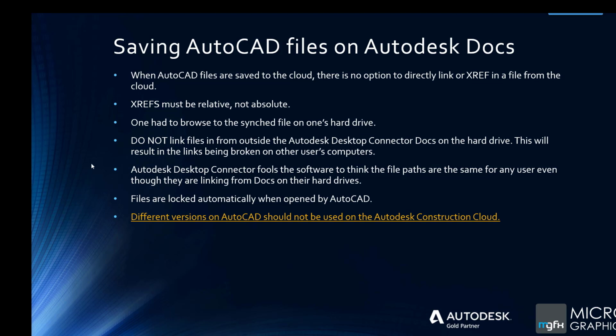So that Autodesk Desktop Connector for AutoCAD and for Civil 3D files is vitally important. When you open them in AutoCAD, they are automatically locked on the cloud, and that means that only you will have write access to them. That's a little bit like Vault.